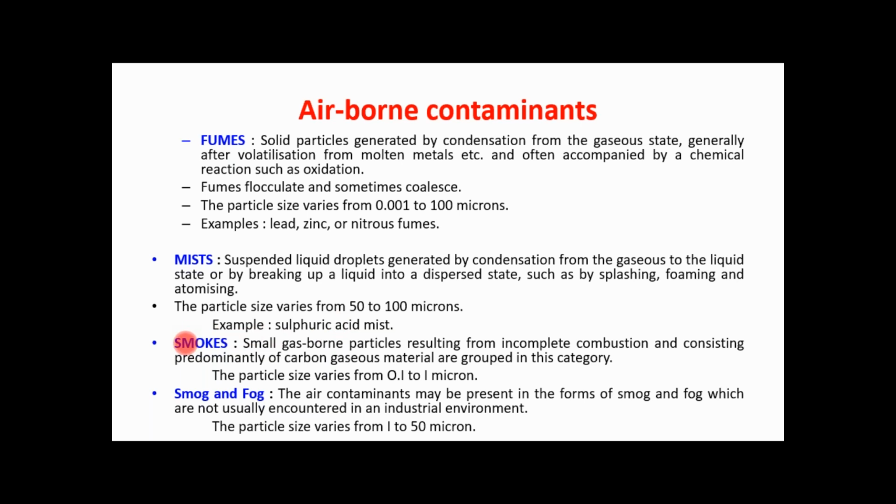Then smoke is another terminology, that is the small gas-borne particles resulting from incomplete combustion. Incomplete combustion is the process where oxygen is not as per the calculations, that is, the theoretical oxygen. If the oxygen provided in the combustion process is less than the theoretical or stoichiometric requirement, then the combustion is called incomplete combustion.